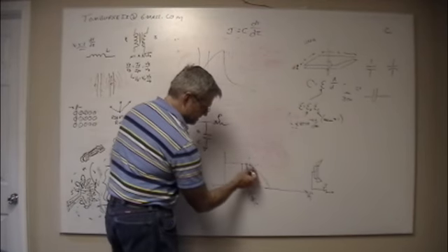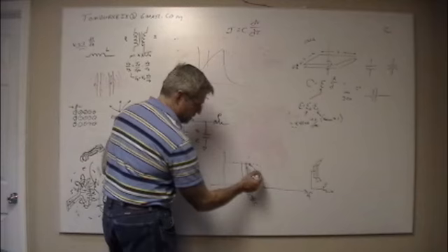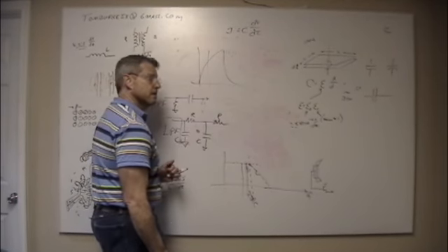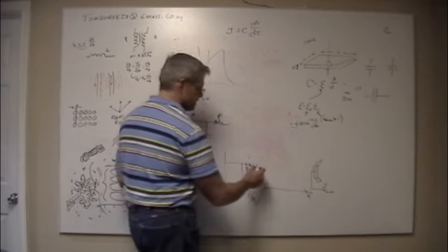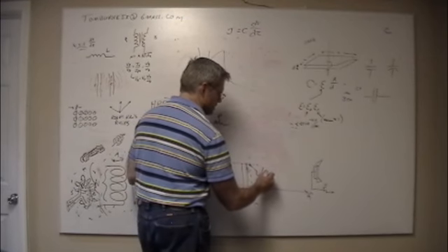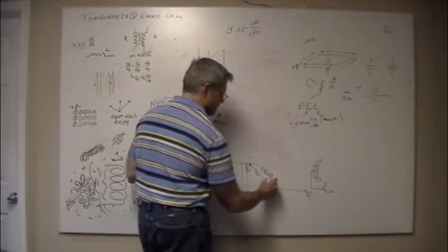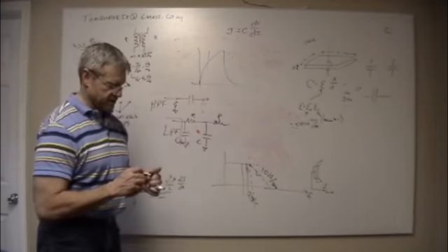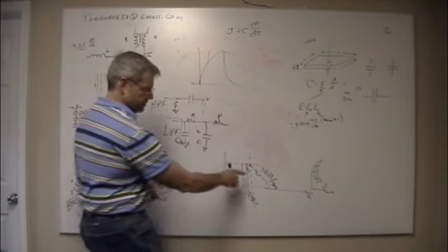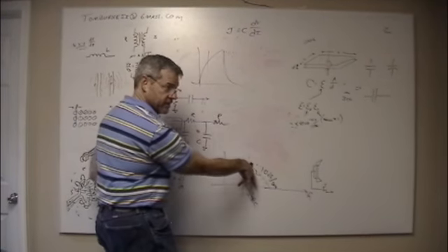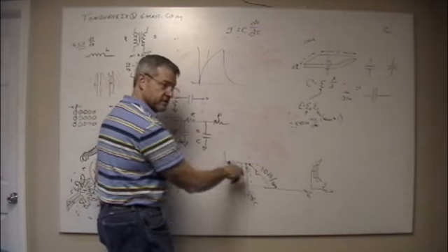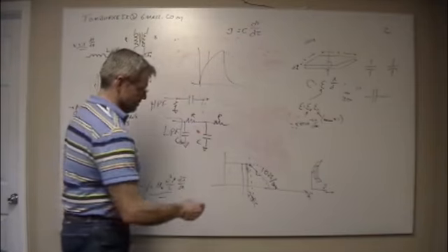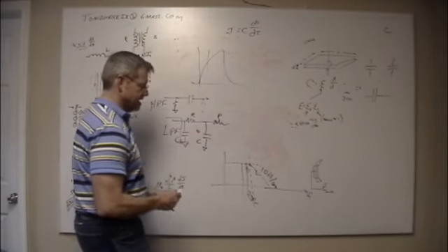And this here, for an RC filter, is at 10 dB per decade. I think it's 10. It might be 20 dB per decade, but I think it's 10. But if you go to a 2-pole, then it gets sharper, it becomes 20, and if you go 3-pole, then it becomes 30. And this gets sharper and sharper and sharper. The more poles, the sharper the...